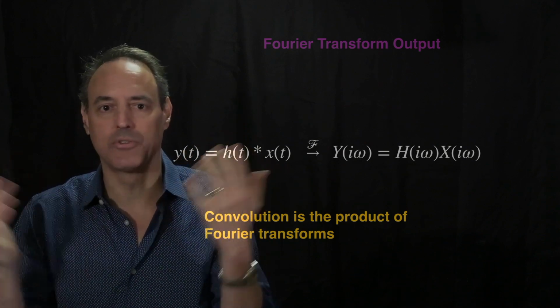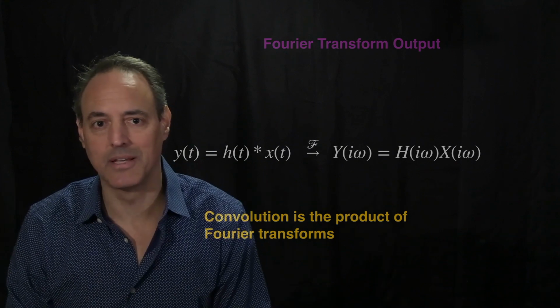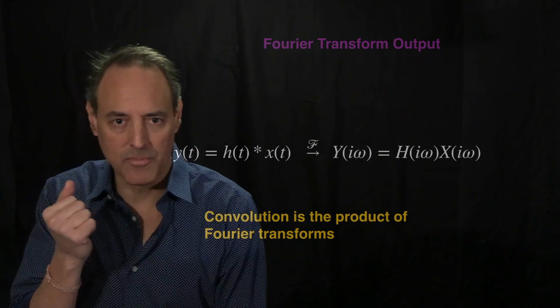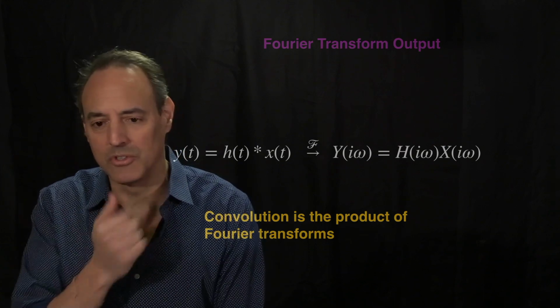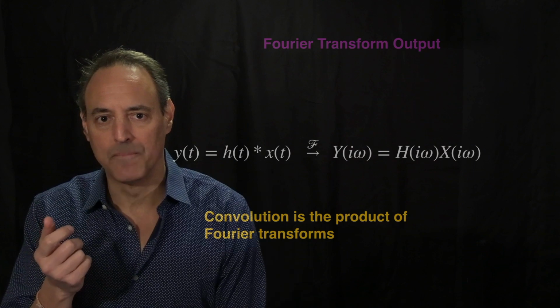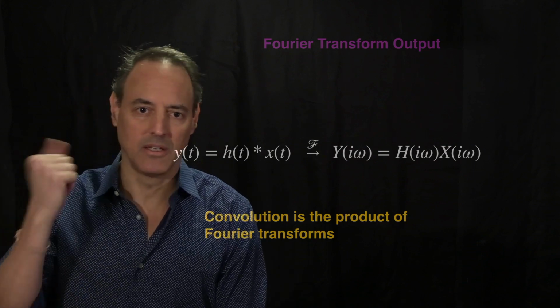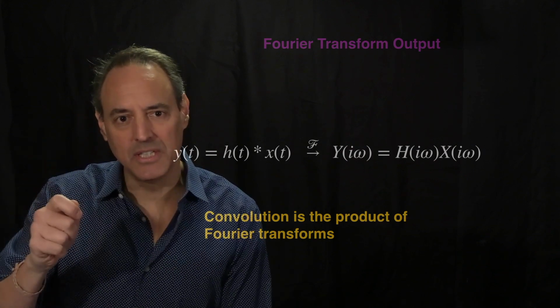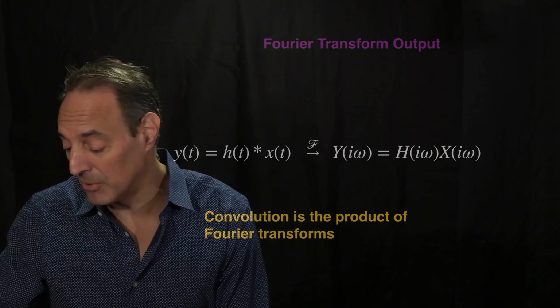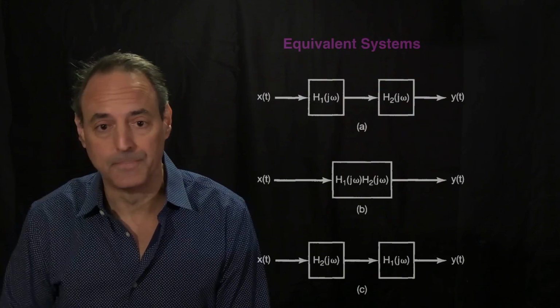because all you have to do is just Fourier transform your fundamental response. And then even as you get new signals coming in, if you've Fourier transformed the fundamental response once, you have it. And so you just take the new signal, Fourier transform it, multiply it against the Fourier transform of the response, and then inverse Fourier transform. FFT, IFFT. It's as simple as that. This is the beauty of this kind of architecture.